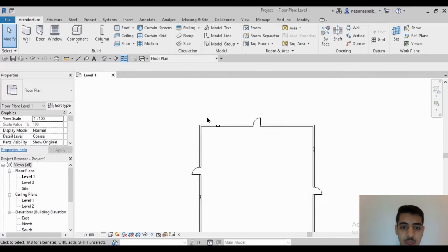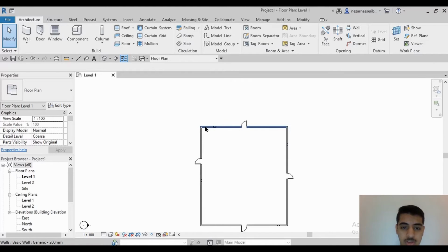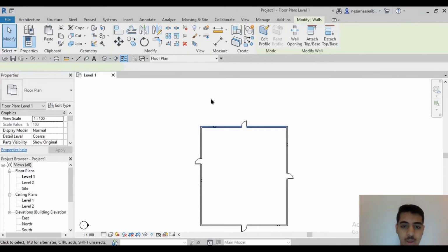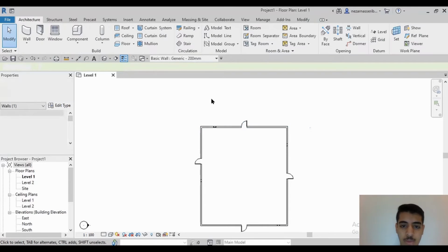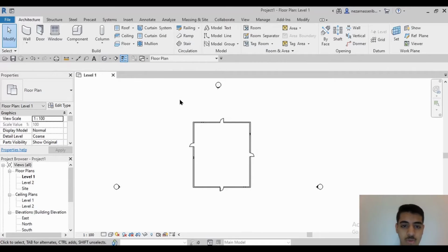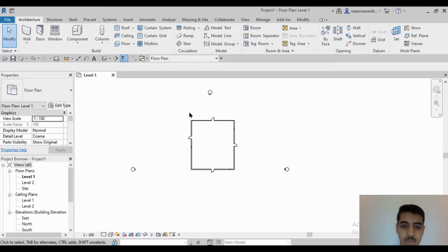Basically, if you want to select something, you can just easily click on it, hover over it until it becomes kind of blue, and then just click on it. That's one way to do it, but there are actually different ways to multi-select and select only categories and different types of stuff. So for example, if you start from the left and keep holding your mouse and scroll to the right, you can see it's starting to select multiple things.